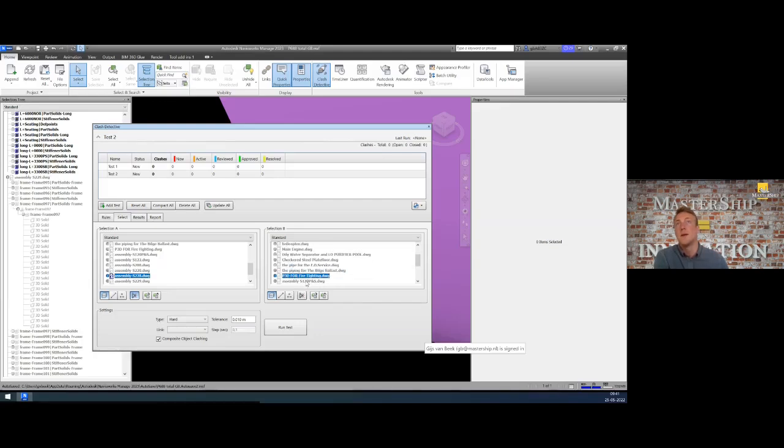If we then run the test, we get all the collisions between the piping of the firefighting system and the solids of the 3D construction model of section 228. But you can also look for internal collisions in section 228, for example a bracket intersecting the hull, or a stringer going through a bulkhead, things like that.